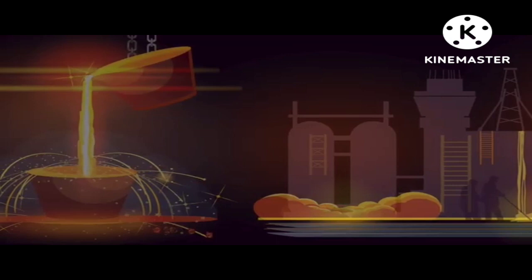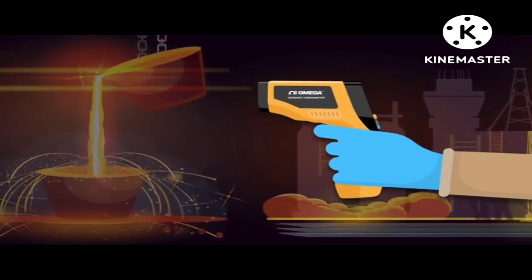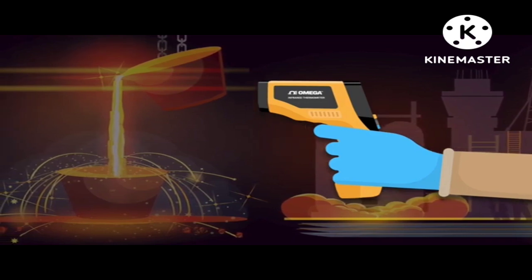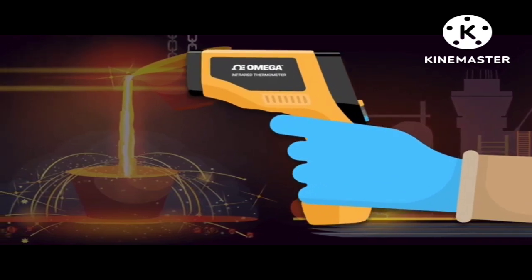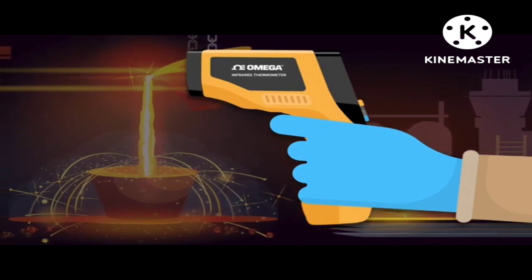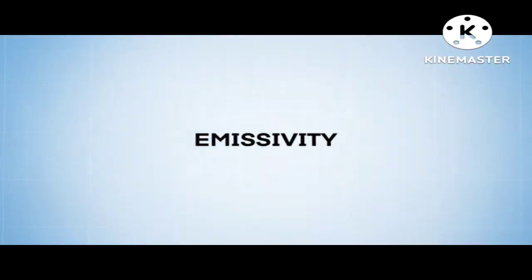The big advantage to using an infrared thermometer is that you don't have to come in direct contact with the object whose surface temperature you are measuring. However, there are some issues to using an IR thermometer that should be considered, especially in industrial applications, like emissivity.